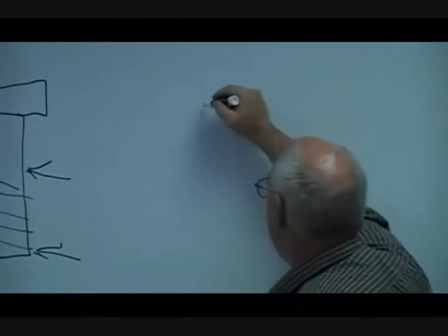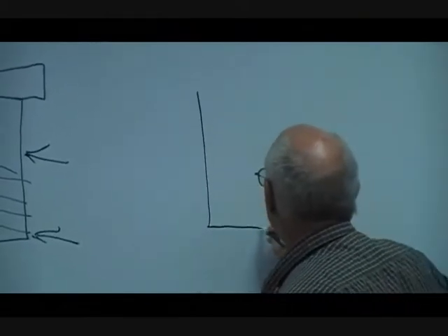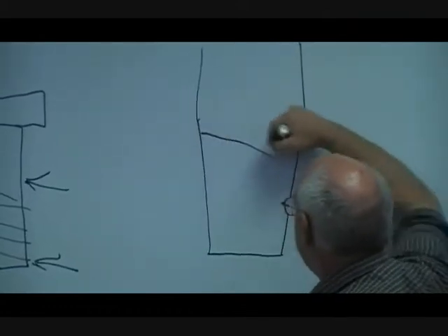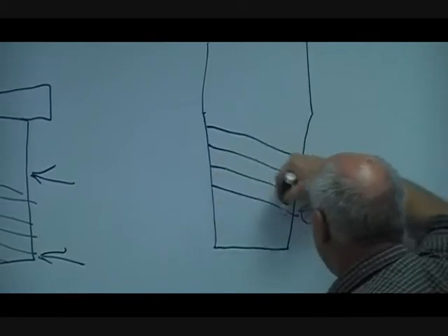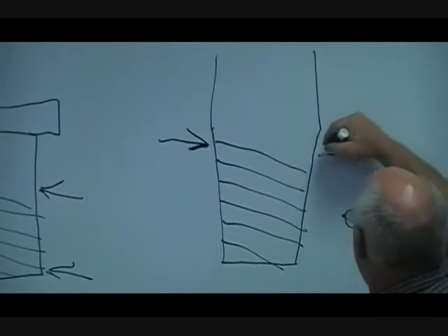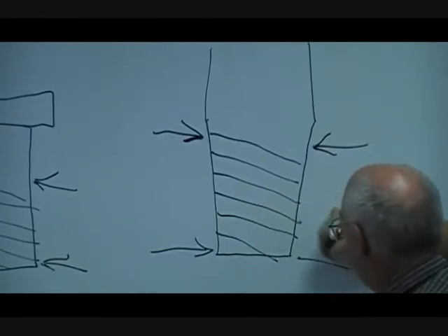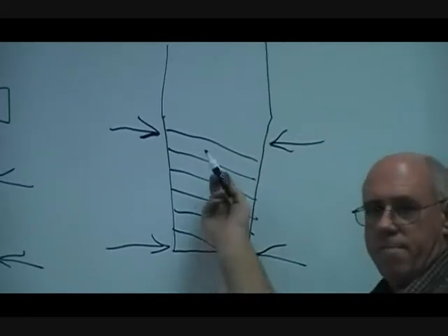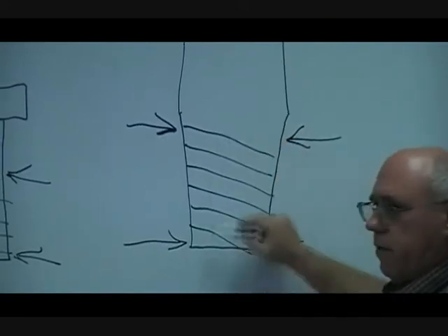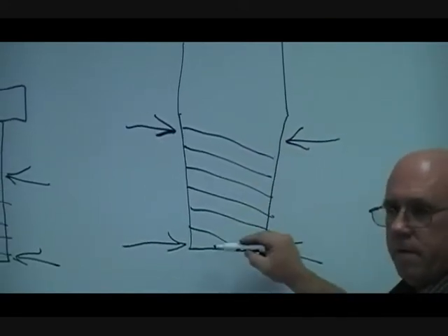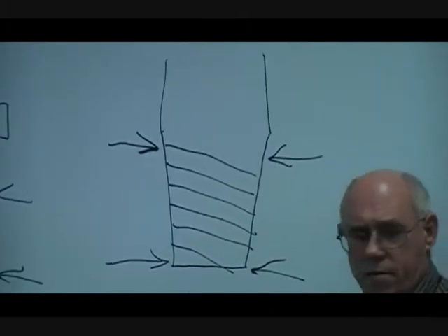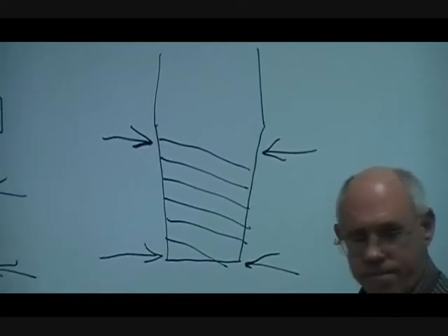If I'm looking at a pipe fitting, then these threads are also so many per inch, but you notice that the diameter here and the diameter there are not the same. It's tapered. Okay? There needs to be at least 7 good threads on a piece of pipe. At least 7. You want to use some type of pipe thread joint compound when you put pipe together.